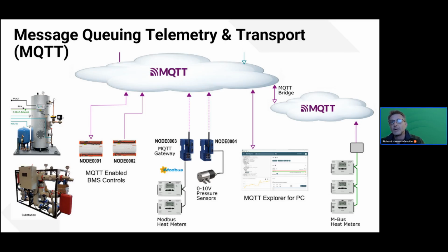It's the default protocol, and an MQTT envelope is the default way at the moment of communicating data points between, say, different BMS points and control systems. We've effectively extended that to cover, well, it already covers everything in the energy centers and substations. So that's the back-end infrastructure that's already in place that just requires turning on in existing panels.